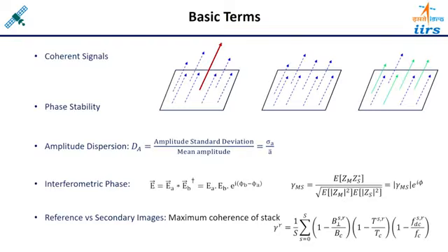For example, if there is some natural environment, let us say a hilly region, where rainfall is happening, or forest patches are there and wind is blowing, the trees move from one position to another. If the image is captured during that time, the phase will not be stable. That is an instability situation. So unstable phase is not suitable for interferometry, especially for multi-temporal InSAR techniques.